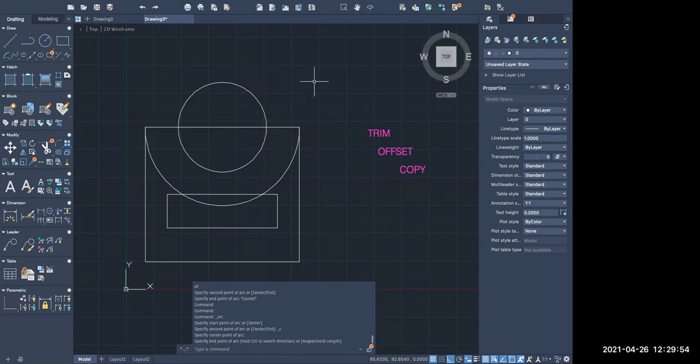But we really need it in the upper side. Okay, so here one more tool I will tell you is your mirror. Here you can see this is the symbol for your mirror. At my cursor location, you can see this is the symbol of mirror. It comes under the modify category of the command. Okay, so either you can click this mirror or you can type here mirror.